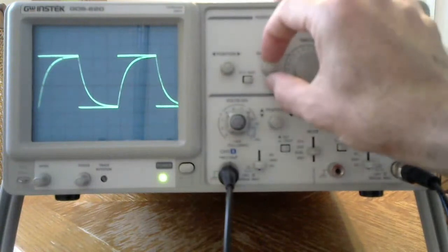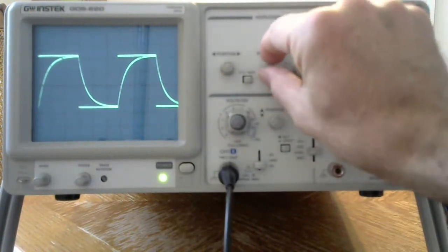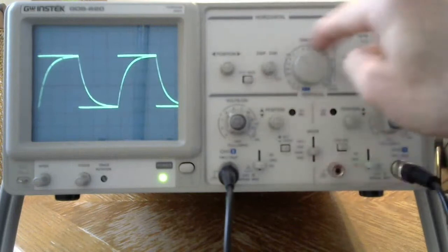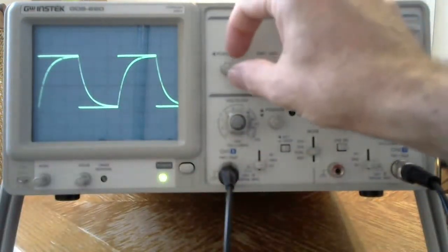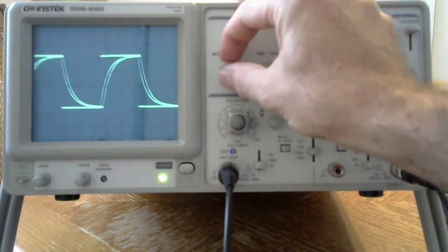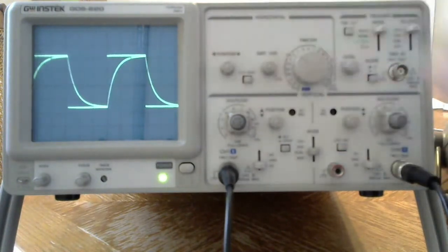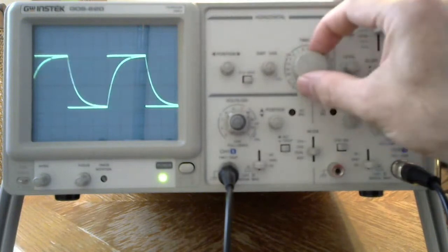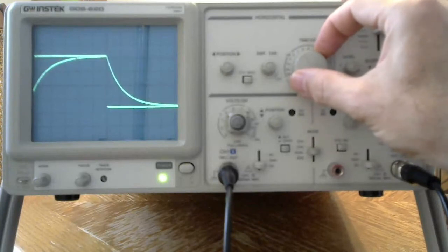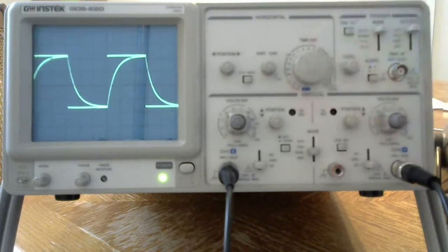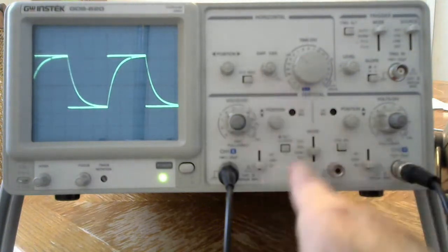Okay, I always want to make sure that I have this fully calibrated, because if this is not clicked into place, then these numbers do not correspond to the actual rate of sweep of this oscilloscope. Okay, so I can move my signal around back and forth using the position knob, and I can zoom in or out of the signal by changing the time base, by changing the amount of time per horizontal division on the screen. Okay, that's my time base. That's the x-axis or the t-axis, the horizontal axis.